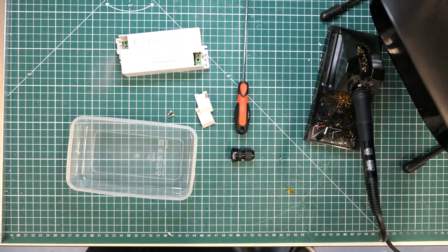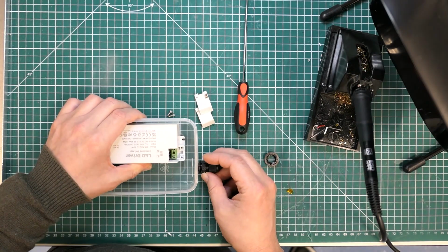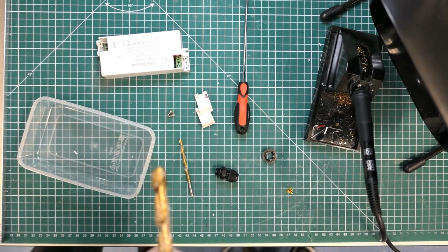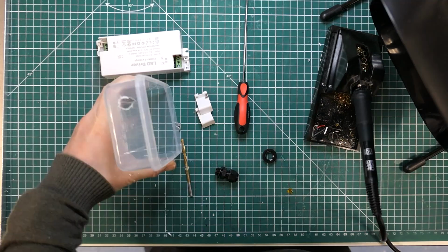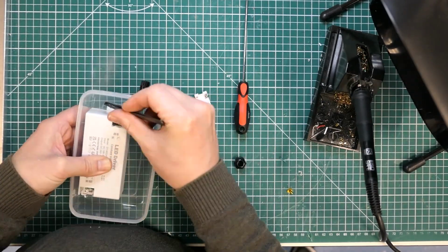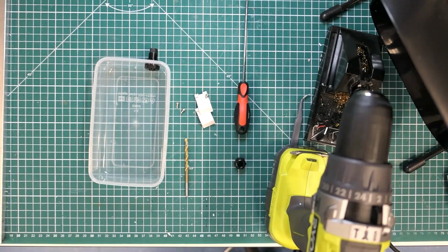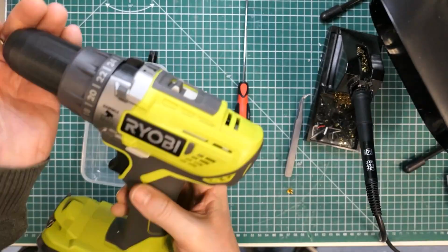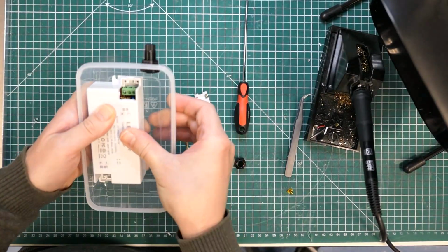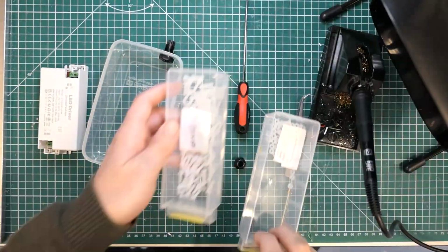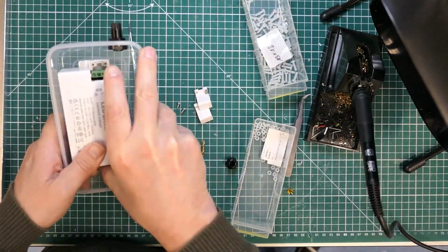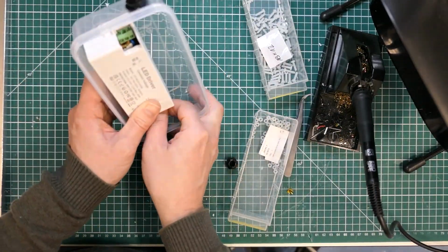As you can see, the power supply itself is really simple. There's just an input and an output. The input, I believe, is somewhere between 100 and 240 volts, so it can do both US and Europe, UK input voltages, and the output's just 24 volts DC. So I'm going to put the mains wire in through a cable gland, and out of this box will be the 2 drains of the MOSFETs, which are going to go to the LED strip, and the 24 volts. So there's going to be 3 wires going through the metal housing and into the actual lamp.